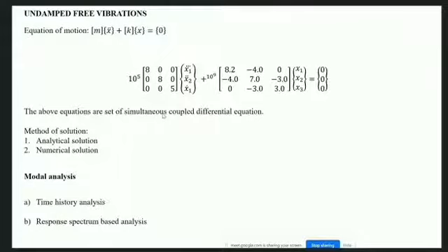That is the input from structure side, and then the time functions which are acting as a weighting factor to the mode shapes, they are basically being decided by the external perturbation, or the time varying force which are responsible for the vibration of the system.